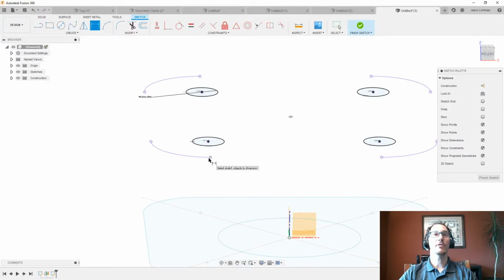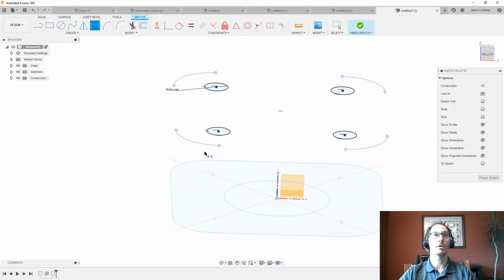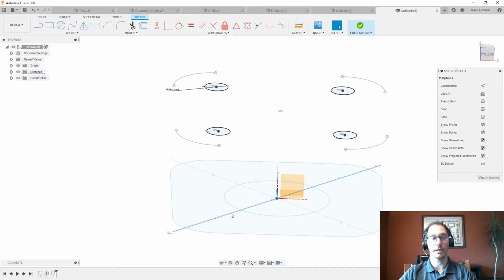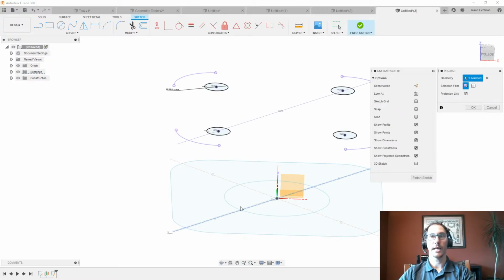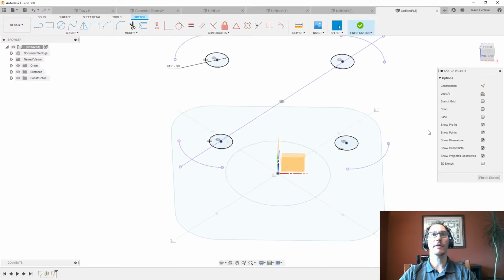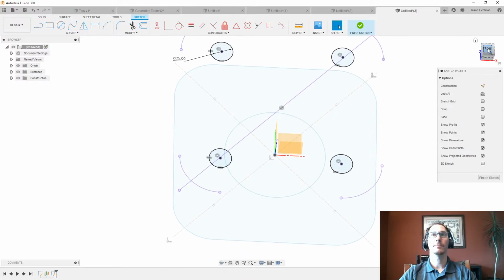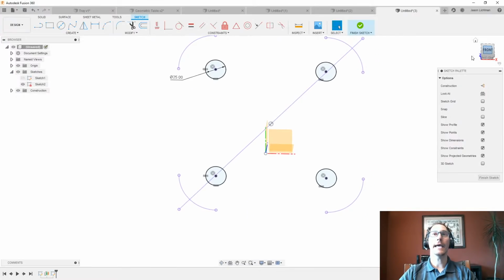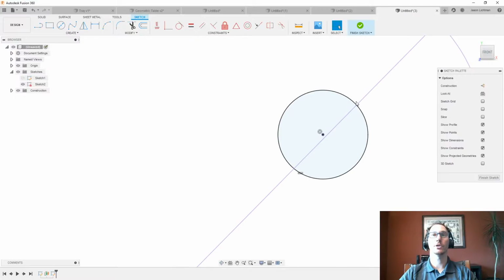Now, if something I projected happens to go through this, let's go and project the center line from the last sketch. Now I have this pink or magenta line going across. Oh, and by the way, let's hide the original sketch, so we were just looking at this new one. Again, just like we were showing in the original, any line that crosses another object is going to turn this into profiles. I have this left half, I have the right half.